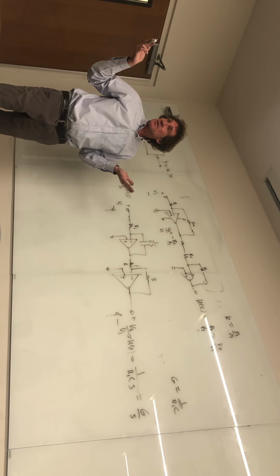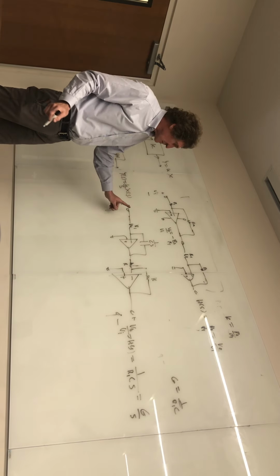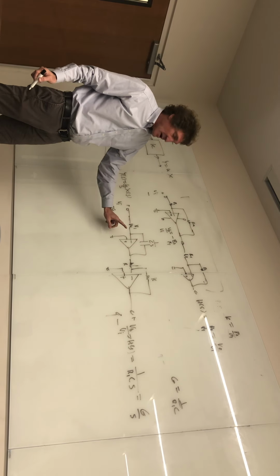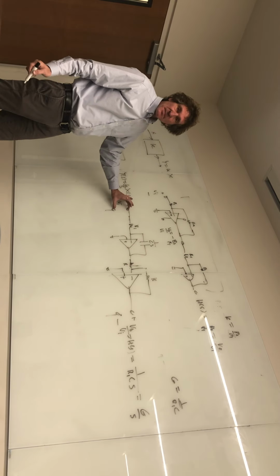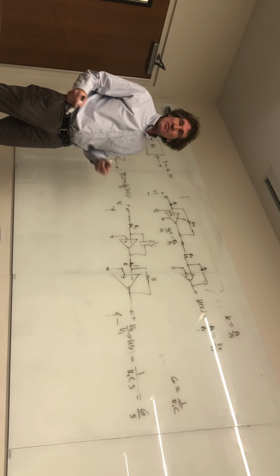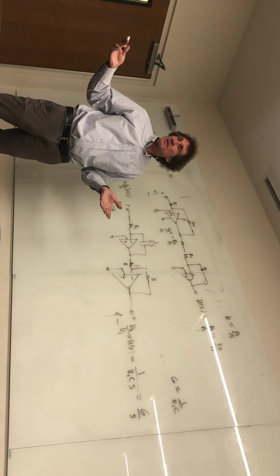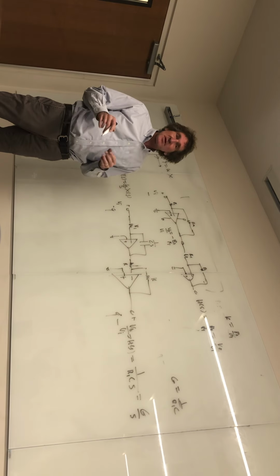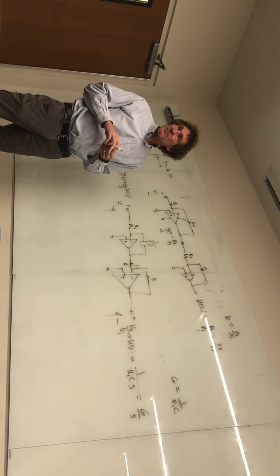And I'm saying this based on practical experience, because here's what happens. For this, right, that's ground. What if you have 20 volts coming in here? All right, you're pulling amps of current. That'll heat up these quarter-watt resistors and burn them out, all right? The other thing is the input to these circuits can get overloaded too. You can fry a transistor.